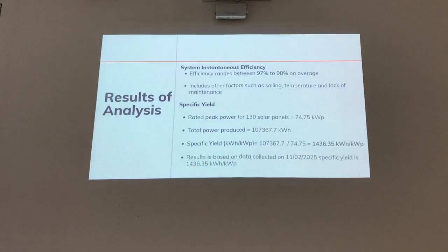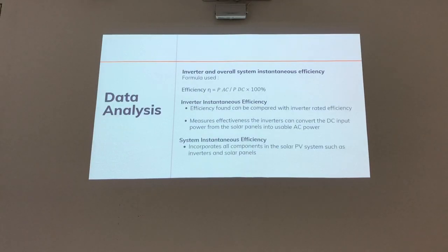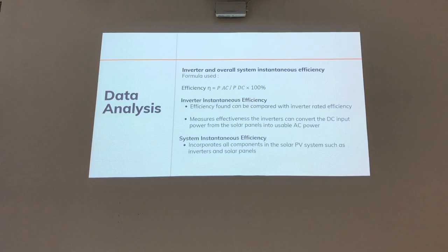Definition of efficiency. We normally don't write an equation all in one line. I assume there is a subscript missing. Why don't you subscript your AC and your DC? Usually P would mean power, and as I mentioned, I use AC as the output and DC as the input. So your efficiency is the ratio of your output over the input, so it's your AC output over your DC input. So it's only the efficiency of the converter itself? Yes, the converter itself.